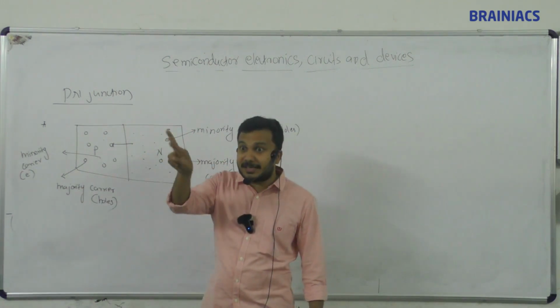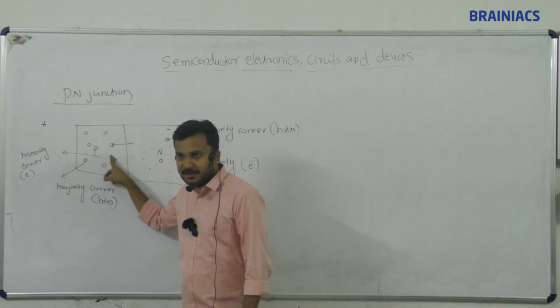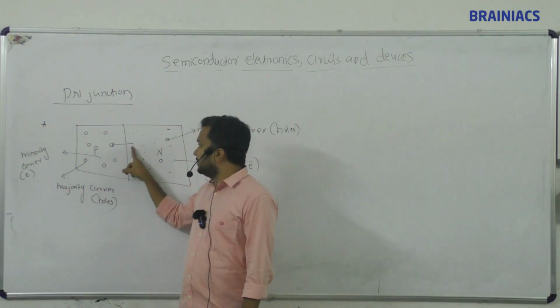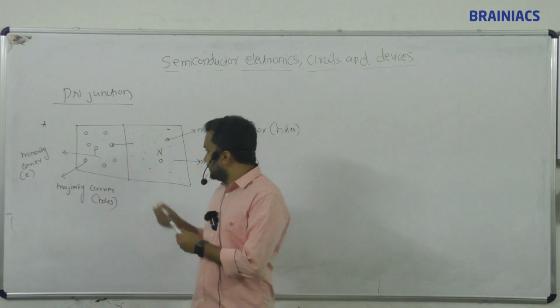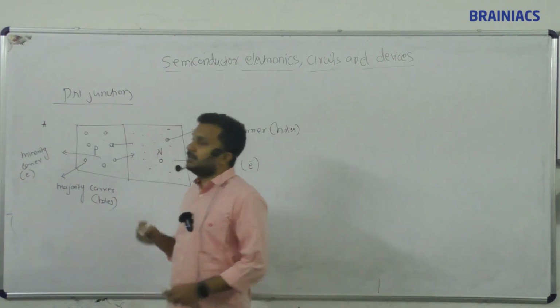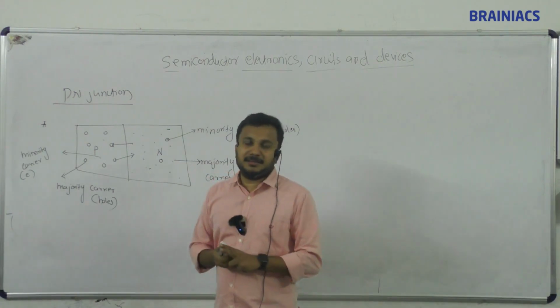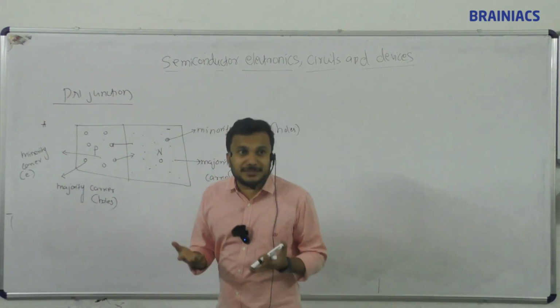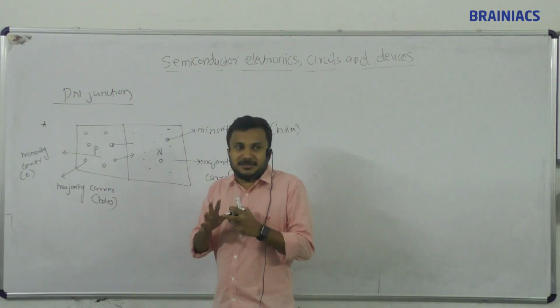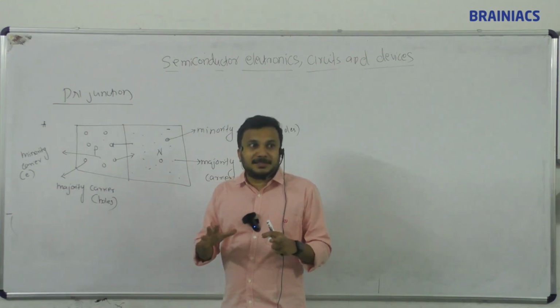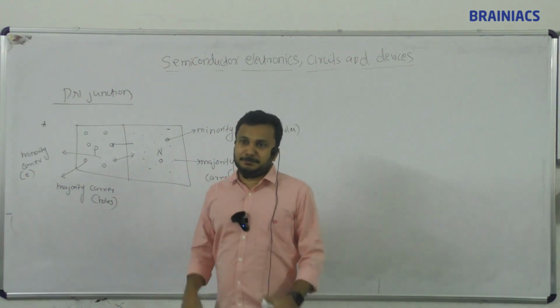That's what it is called, recombination. It's combining again. So whenever this electron meets this hole, it will combine. Similarly, if this hole is moving, it will meet another electron and it will recombine. Once it is recombined, these electrons and holes cannot move because its energy is less, because it is stable.